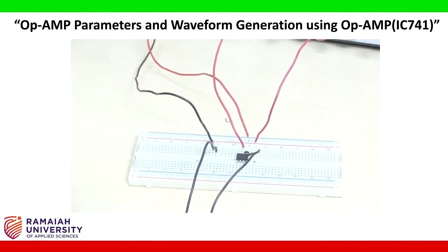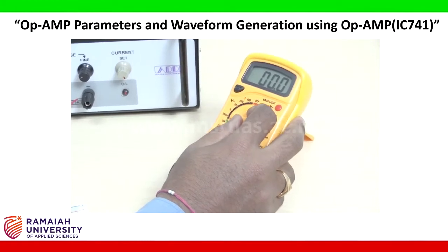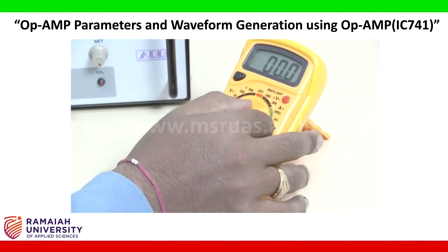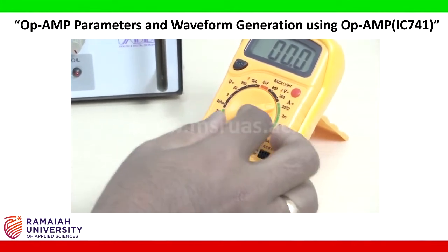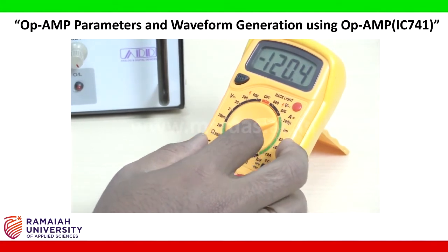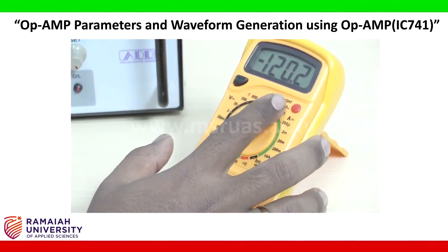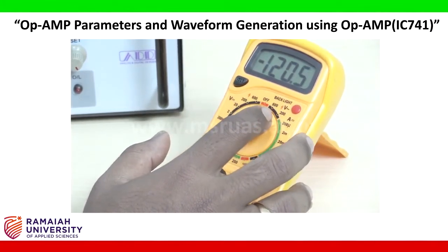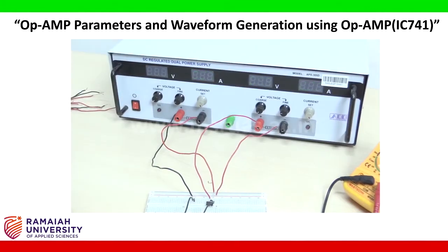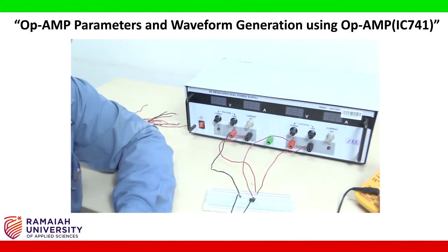Okay, now let us switch on the system. We are measuring the current. We need to tune the voltage to current. This is the microamp current I am going to measure. It will show us some 120.3, so it is 120.3 microamps that travels in terminal 1. Switch off the system. In the same way, we are going to measure the current in terminal 2.